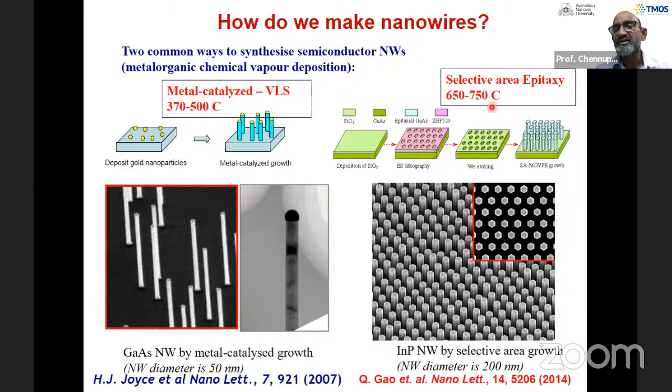And those are the temperatures. Typically, we grow the epitaxy layers, for example, introduce the gases needed for the growth of indium phosphide nanowires, for example, trimethyl indium and phosphine. And then the nanowires start growing wherever these holes are there. You can see the ordered patterns of these nanowires, because you created ordered patterns of these holes here. You can see the SEM image of these indium phosphide nanowires, and you can see the top view showing the beautiful ordered patterns with beautiful hexagonal facets being nicely seen.